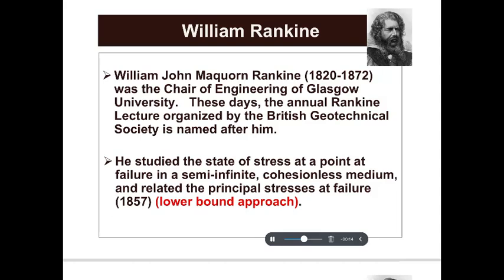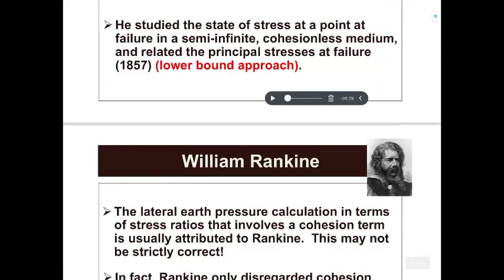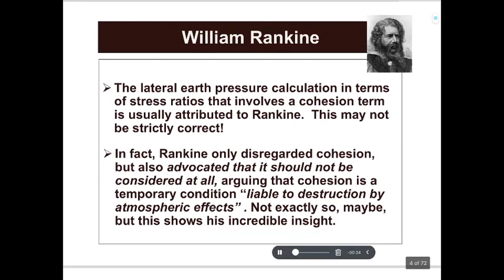He studied the state of stress at a point at failure in a semi-infinite cohesionless medium and related the principal stresses at failure in 1857. This is the lower bound approach in estimating the lateral earth pressure. The lateral earth pressure calculation in terms of stress ratio that involves a cohesion term is usually attributed to Rankine. This may not be strictly correct.